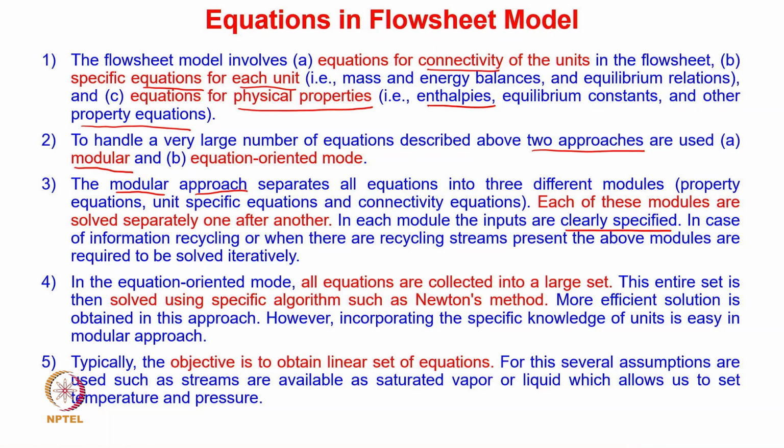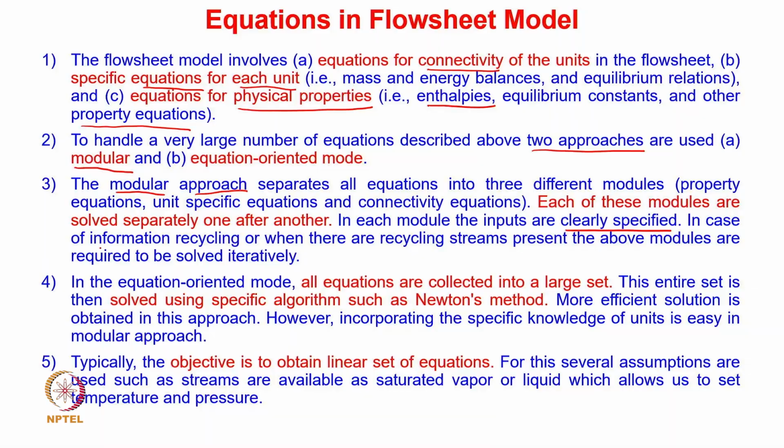Very often, when we solve the entire chain of modules, we see a discrepancy between the output of one unit and the input of another unit. In order to reconcile these discrepancies, there is often information recycling, and whenever information recycling is there, we require an iterative procedure to solve these modules. Also, in some cases there are recycling streams present in the problem. In such cases also, an iterative procedure is required for solving the modular approach.